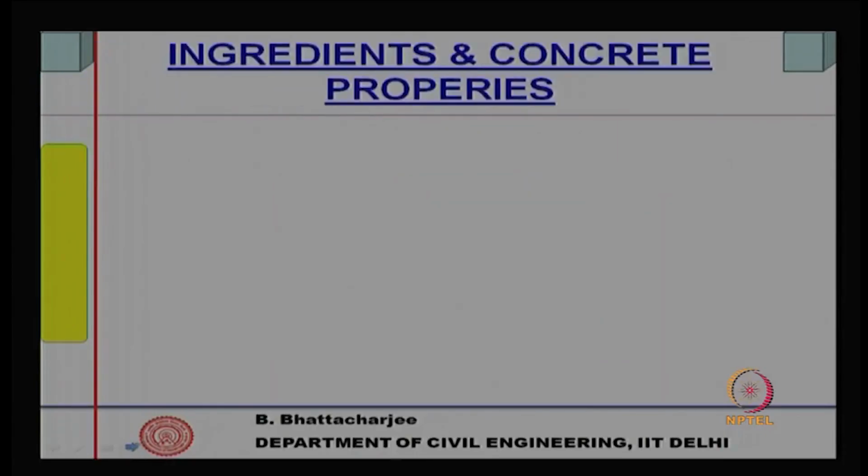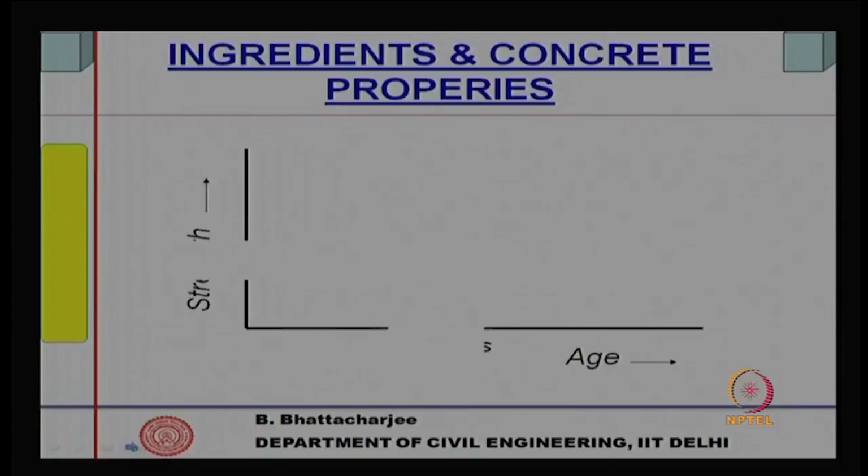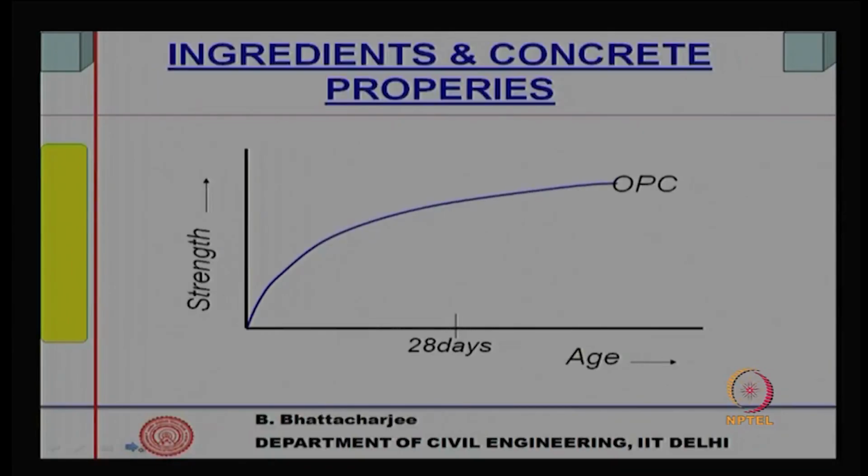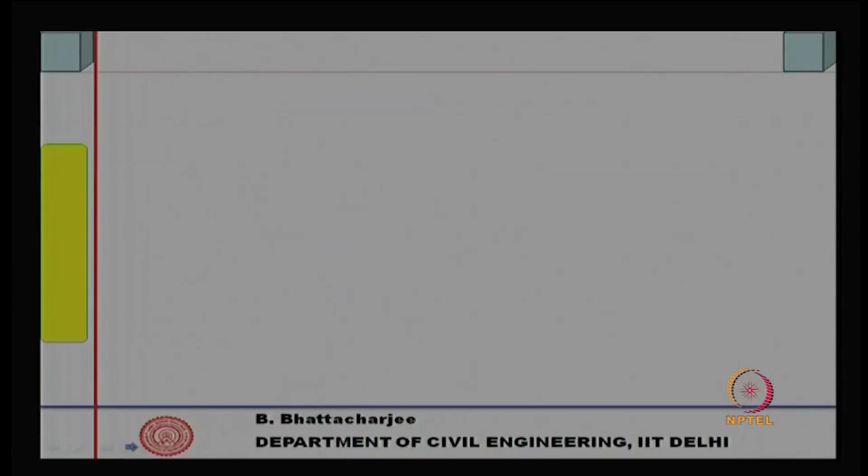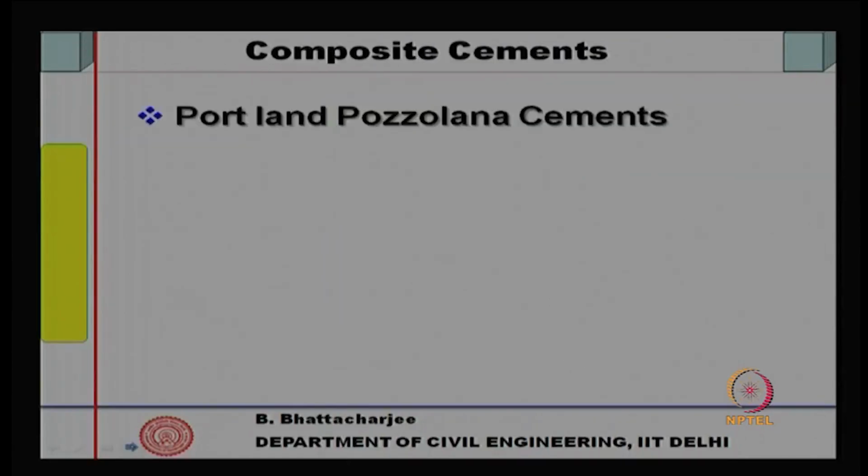So, blended cements are produced from this. One important issue is that such cements, when you produce by intergrinding gypsum, clinker and the pozzolana, their initial strength is lower, but long term strength is better, particularly with fly ash. And so is the case with slag, but silica fume can show you high early strength as well. We will discuss this sometime later on.